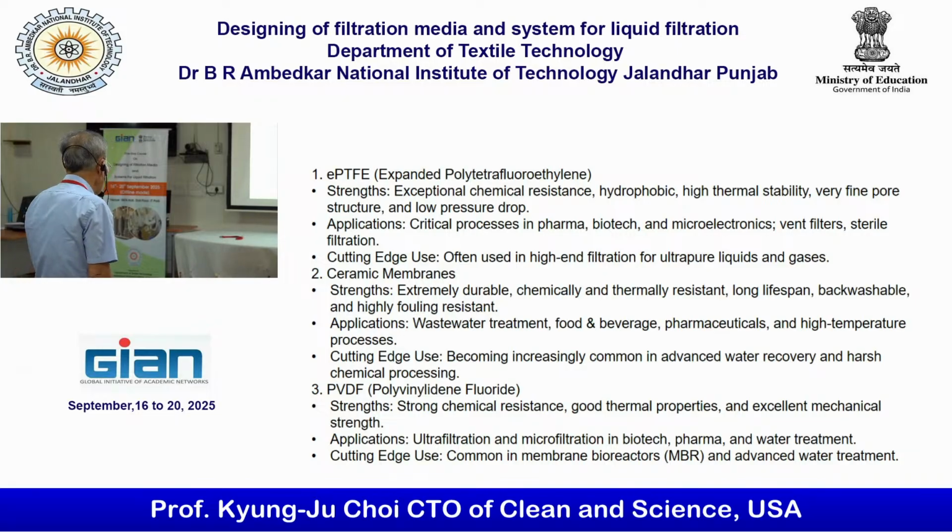Yeah. Ceramic membrane is getting popular, and strength: extremely durable, chemically and thermally resistant, long lifespan, backwashable, and highly fouling resistant. That is true. See, ceramic material, you can burn it and then reuse it. Application: wastewater treatment, food, beverage, pharmaceutical, high temperature. Cutting-edge use, becoming increasingly common in advanced water recovery or harsh chemical processes.